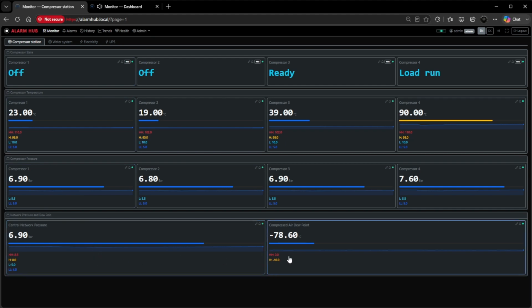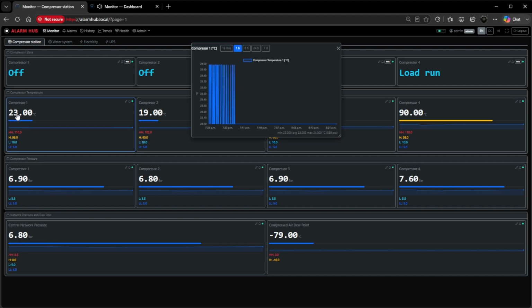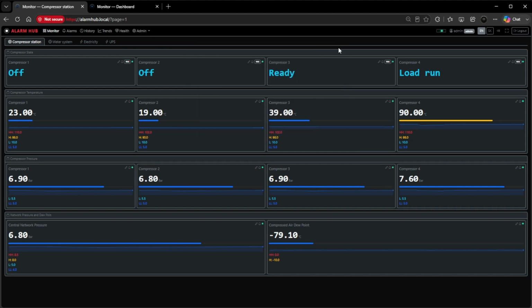Here's the idea. Every machine in a plant already has its own HMI, the panel right beside it, showing the operator all of that machine's tags. But step up to a central control room, and the dispatcher there doesn't need hundreds of signals from every machine. They need the few that matter, a handful of critical values from each line, gathered in one place. That's what this hub is, a higher layer of monitoring.